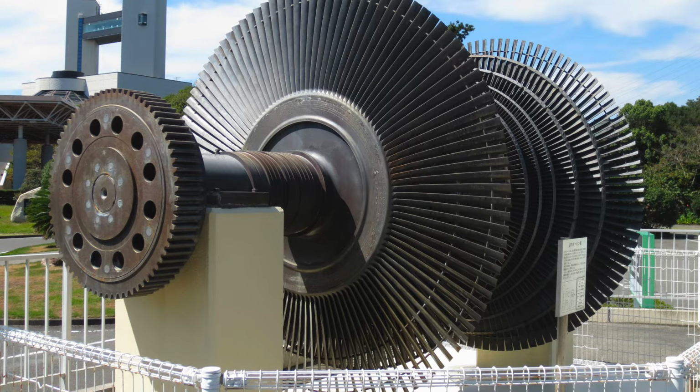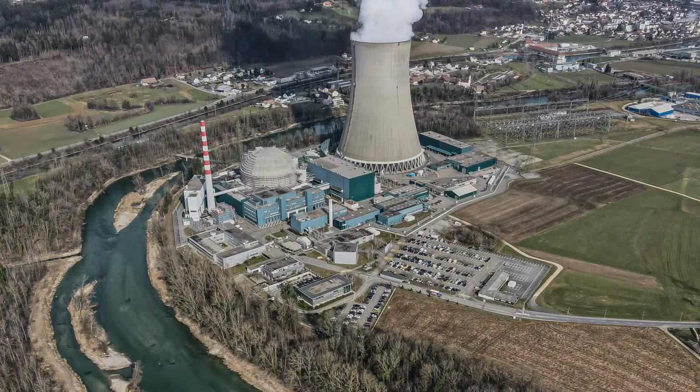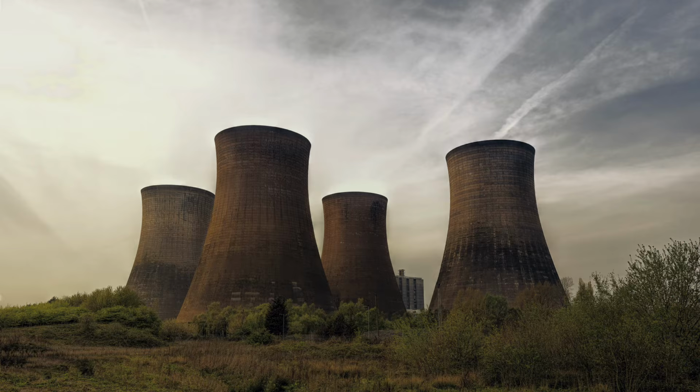A nuclear plant is rated for about 40 years, longer than a desalination plant's 25 to 30 years. Depending on their material, thermal desalination processing tubes have to be retubed every 10 to 20 years. Reverse osmosis filters and systems also have to be replaced at regular intervals, so the integration design has to take this maintenance cost and human effort into consideration.